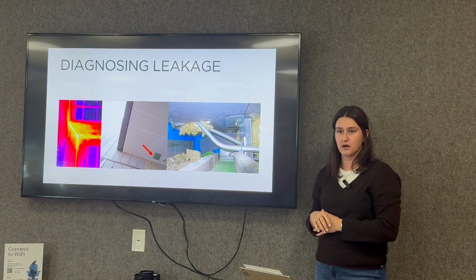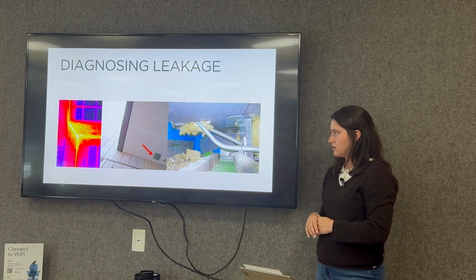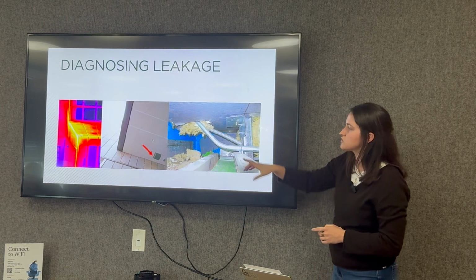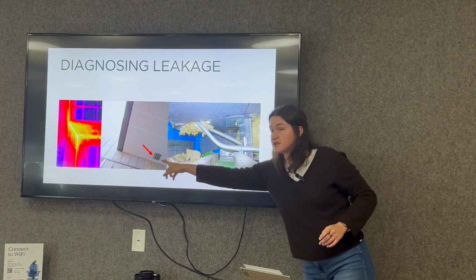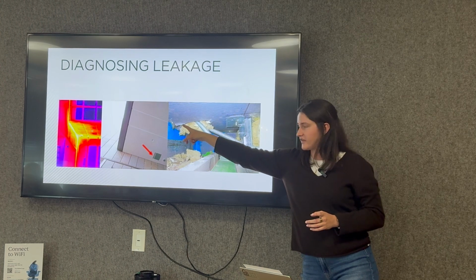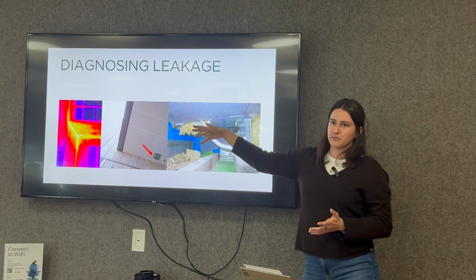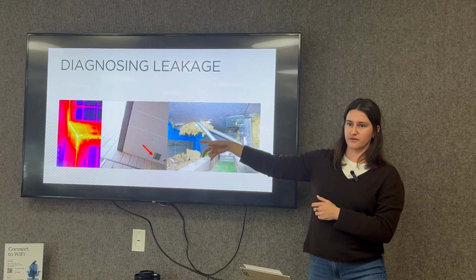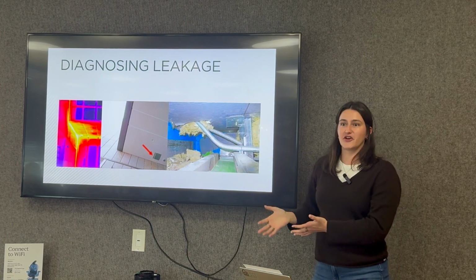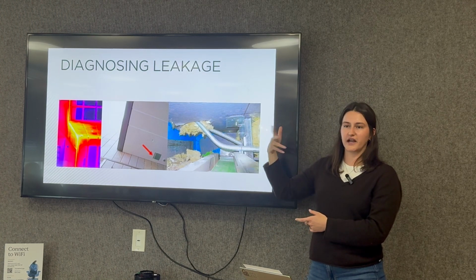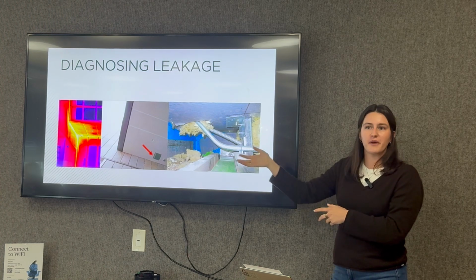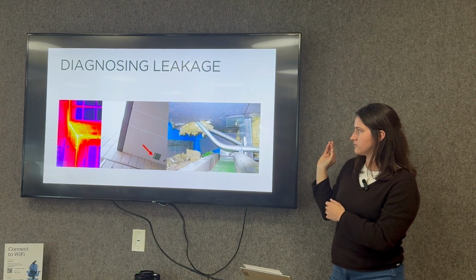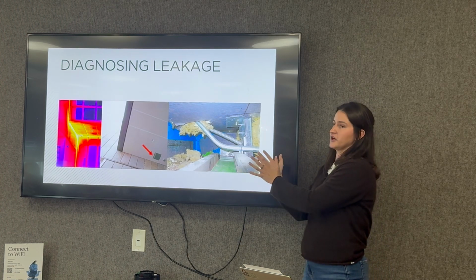Was there a detail for that conduit at the time? Or was that delegated to the security contractor? I believe that would be a security contractor, right? So this would have a typical architectural detail for the rising wall, and then maybe the soffit coming into the rising wall, which shows the air barrier here and then continuing along this way. But right where we typically run into issues is where after all of that's said and done and everyone says this looks good, then the soffit is enclosed with some sort of trim, and then someone comes back and says, I need to install the security camera, I need to make an opening in this wall. Right, and the general contractor is like, okay, go make the opening in the wall, and then when we don't go back and check, this is what happens. And so this condition here is essentially, for the lifetime of the building, just dollars that are walking out the door in a condition that we can't see.